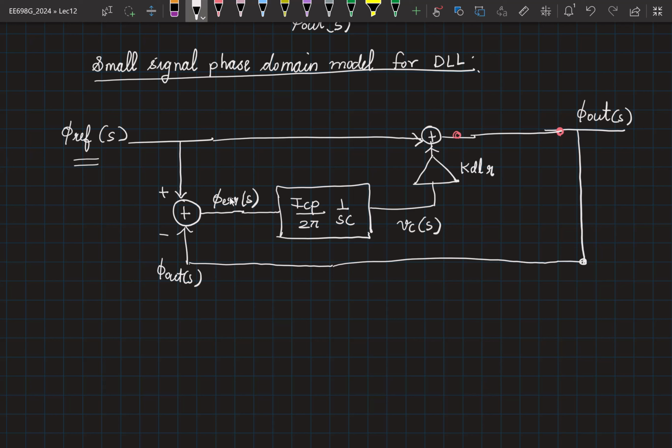If there's a very high frequency variation in your small signal, then you should technically choose your TRF such that you are able to detect it, because your PFD can detect it only every TRF. Now if the variation of phi F is happening much faster than what it can detect in one TRF, that itself is a problem. Or the small signal variation is not changing that fast, but the loop is responding to that slow change also very slowly.